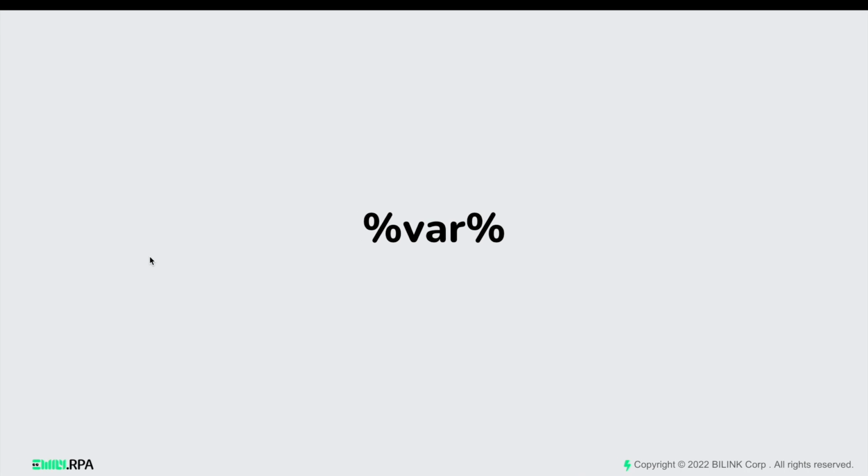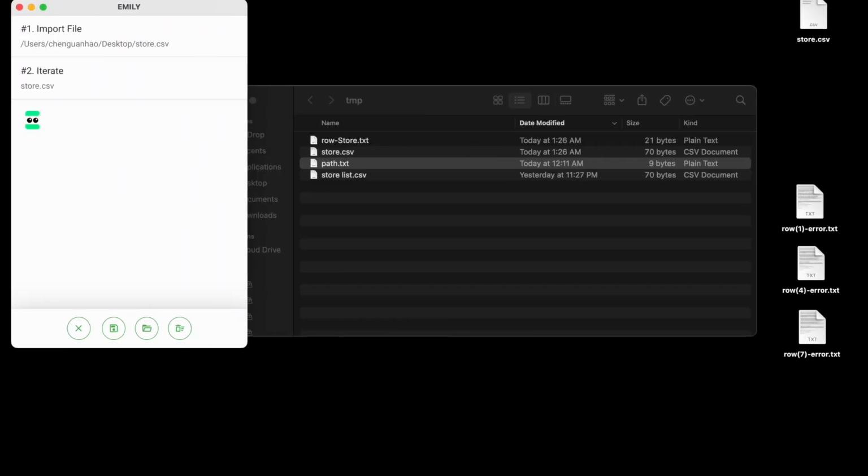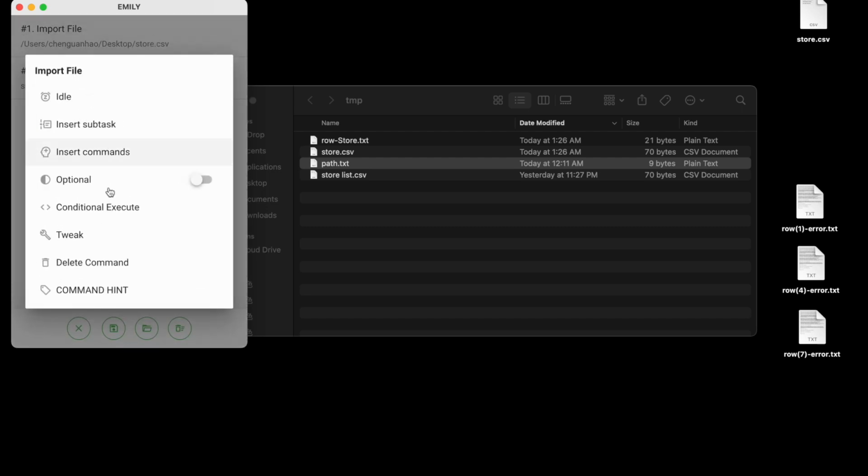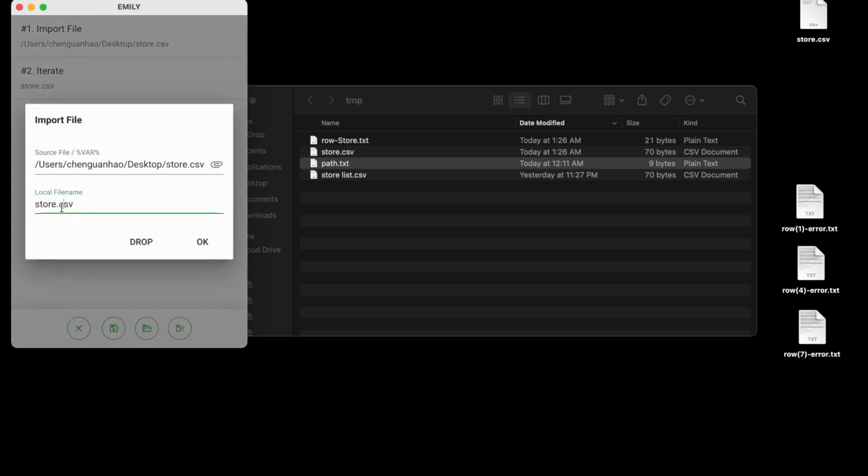There are some common errors that you may see. The first one is that you may have changed the name of the imported CSV file, or for some reason the source CSV is not produced, leading to a direct failure of the skill. When you open the workspace, you'll see an error file stating iterate fail. In this case, you should check the file name.